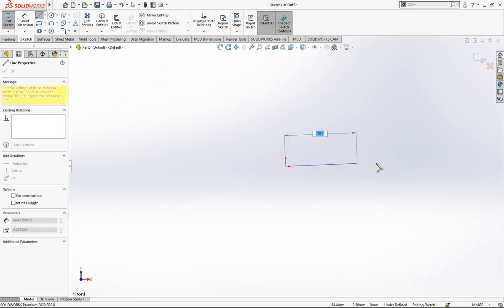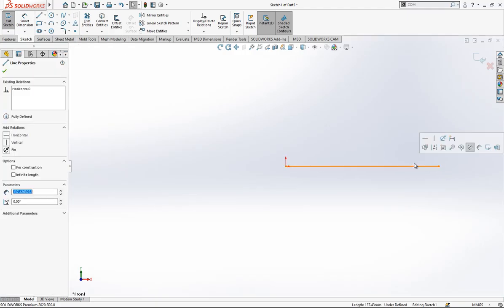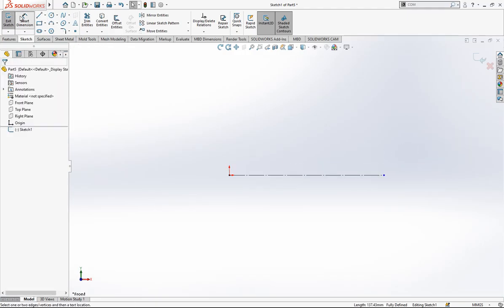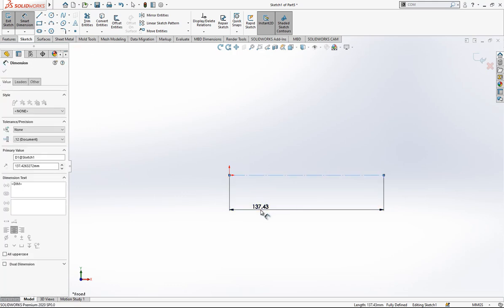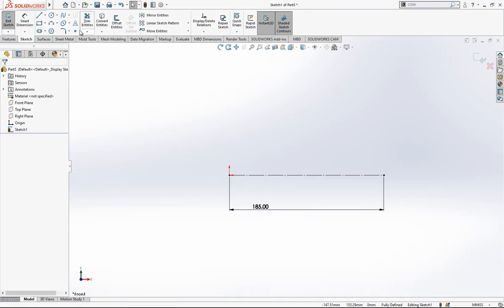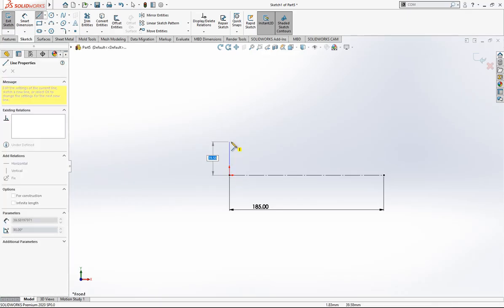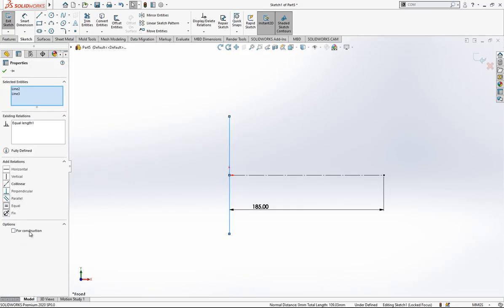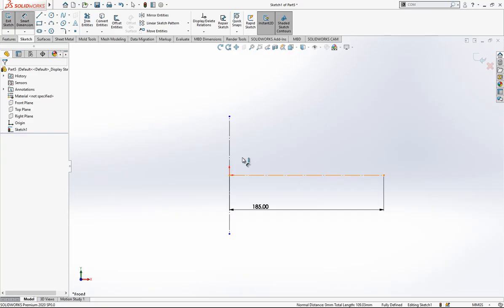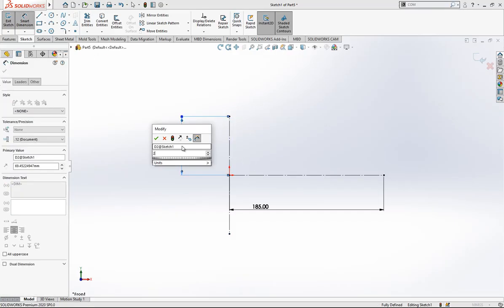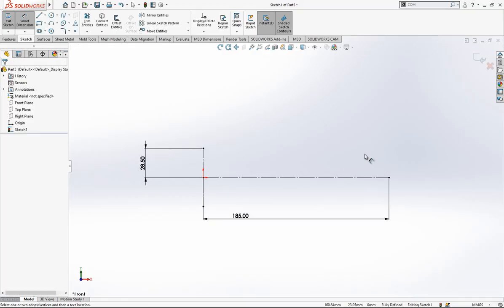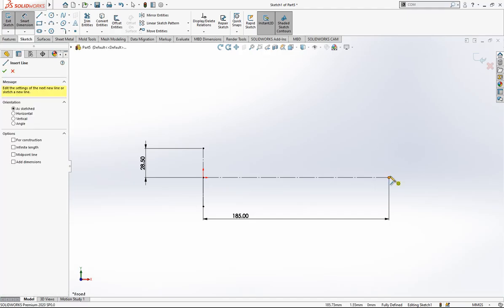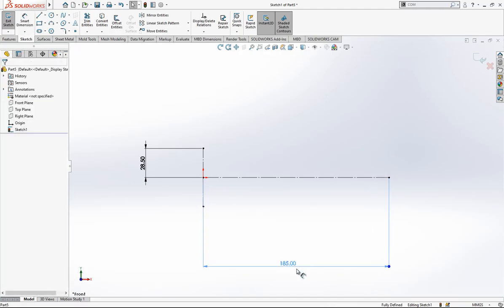As always, first we are placing a construction geometry. This geometry will be 185 millimeter, and then here two more. We click on them with control and we say they are equal, and then the height from center 28.5, and for now we can start with other operations.